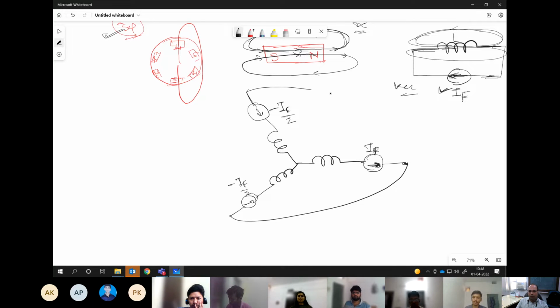Yes. This is aligned along the R axis, this is aligned along the Y axis, this is aligned along the B axis. Correct? So this is how we can form our system. Or let's say Y is here and B is here to maintain similarity to our stator arrangement. So this is the arrangement for how we can model the magnets on the rotor of the PMSM.